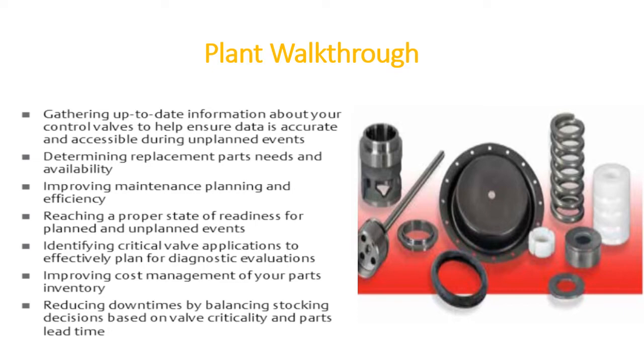Unfortunately, there are only a few major valve vendors who have a specific part number for all the spares. Otherwise, all other vendors supply the spare by the name of the valve, so they make the spares almost unique. So for each valve there are unique spares. But if you carefully study these things, it is not like that, and there are certain models or certain specifications that can be followed by a group of valves.